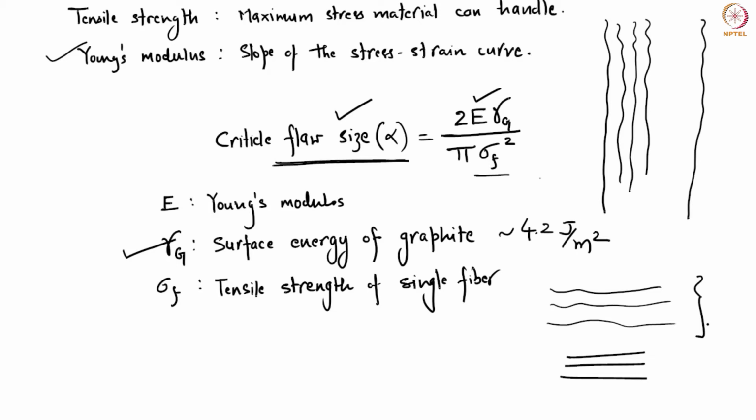Okay, so you have turbostratic structures. Now you increase the temperature. What will happen? Some of them may actually align and form graphite crystallite. However, now when this space decreases, because the spacing between the sheets is now decreasing, there may be some voids created because we are not supplying any material from outside while our structure is shrinking, and it is shrinking in random ways. It's not necessarily one big graphite crystal that is forming. So you may end up getting certain voids or certain flaws.